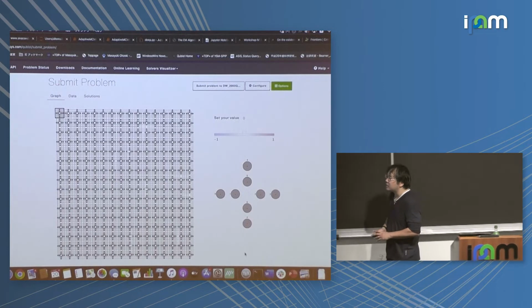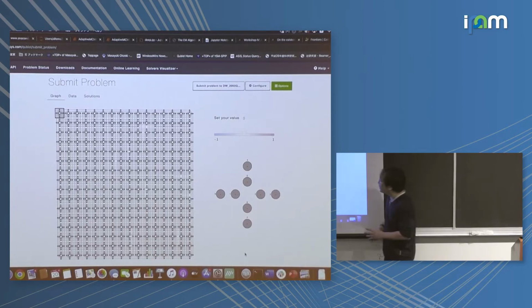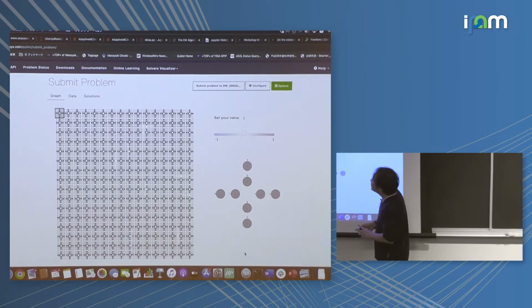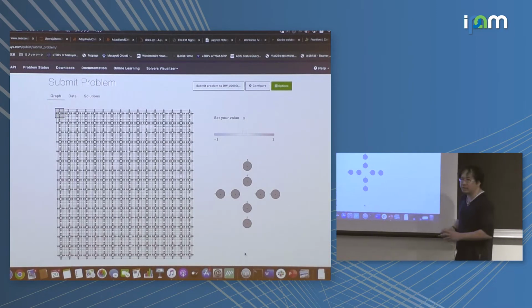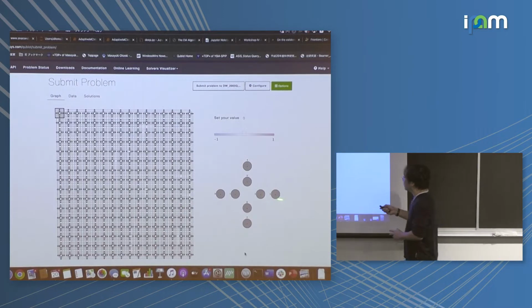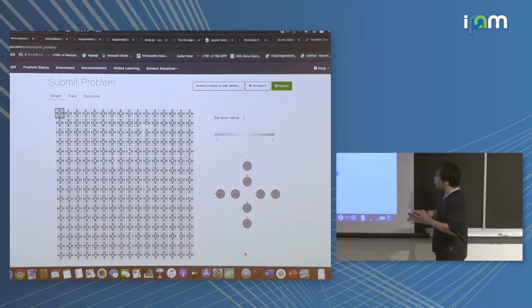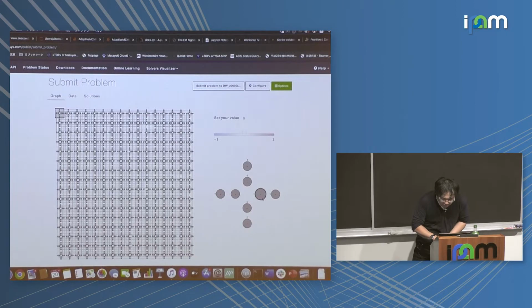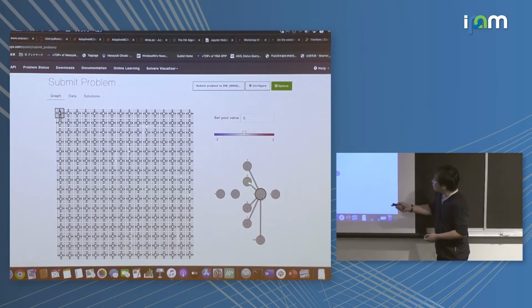So here is the chip of the quantum annealer. You can count the number of qubits: about 2,048. This rectangle denotes a unit like this. The vertical and the horizontal are 4 by 4 qubits, so 8 qubits is 1 unit. And you can access each qubit directly. Then you see some connections between different qubits.